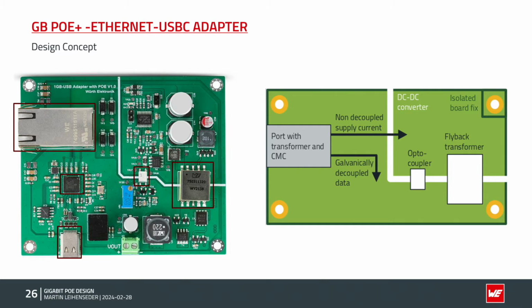And then we have here a feedback loop. This is an optocoupler. And you can also see this on the right side. Here there are some clamps where you as a customer can take out the current for your needs. And here we also have a chip and a DC-DC converter. And this DC-DC converter converts the energy, the 3.3 volt that we need for the chip.